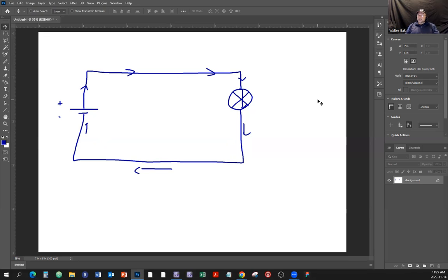However, there is such a thing as a long branch and a short branch, and we talked about it a few lectures back. It has something to do with the physical length of the conductor in the electrical installation. But it's not a long circuit, it's a long branch. So it's a different thing. Right? Okay, so in order for the light bulb to be on, we have to have a closed circuit. Well, we're going to have to accomplish that with the three-way switch.